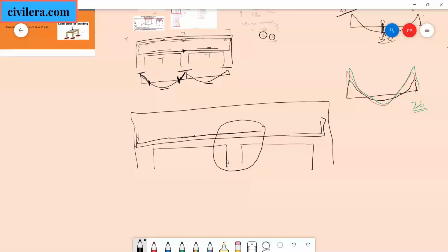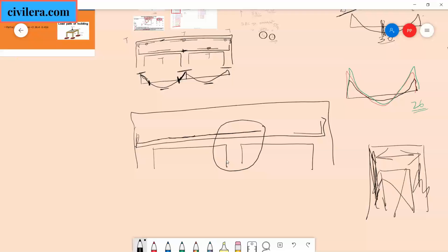If you look at shear walls, the coupler beams, say when you have a lift, you will have something like this. This is a wall, this is a wall, and then this beam is a very short beam. It's the lift opening, the door of the lift, and this top portion is like a coupler beam that might have these kind of challenging force patterns. So you will have to carefully see all that.